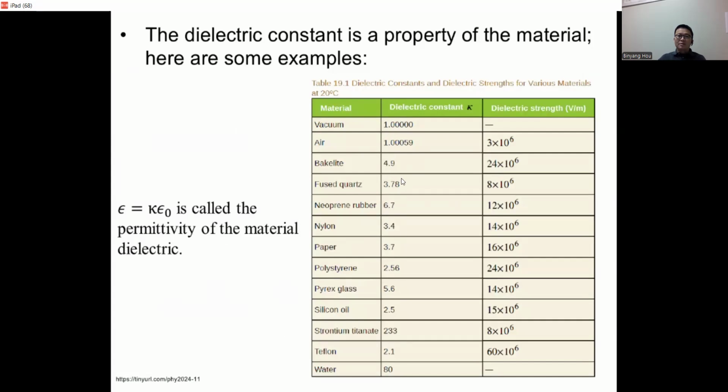Okay. Now, insulators are not always non-conducting. If you apply a lot of voltage, electric field, at the two sides of a material, it will break down at a certain point. To break air down, you need 3 million volts per meter of electric field to be applied. And for other materials, you can see they are all on the order of million volts, so very high voltage.